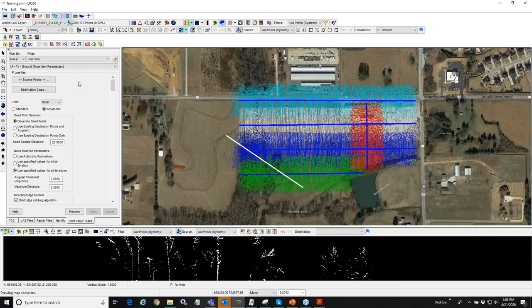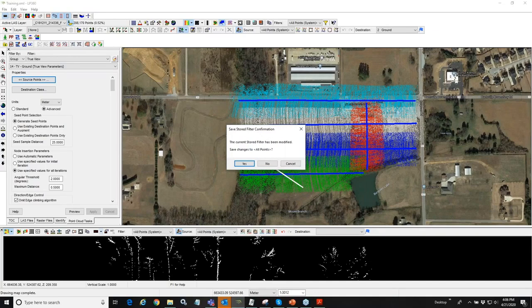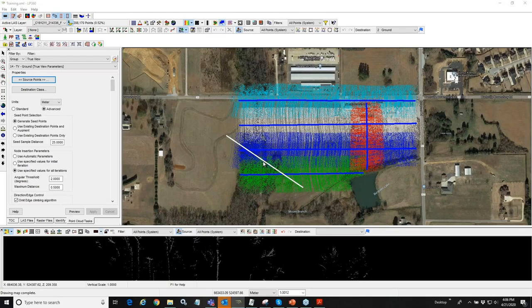If you're not familiar with classes, that's just a standard thing that people work with in LIDAR data. There's a standard class table that's part of the ASPRS LAS standard. Class 2, for example, means a ground point. Now, there's a lot of power in this, should you need to do some additional tweaking or configuring of the point cloud tasks.